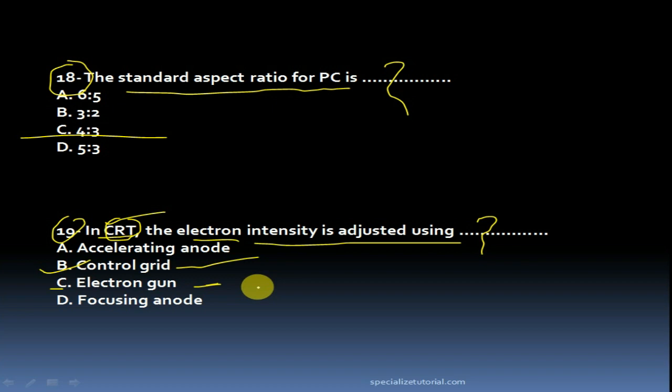So now the question is, how does the electron gun work? An electron gun starts with a small heater, a lot like the hot, bright filament of a regular light bulb. It heats a cathode, which emits a cloud of electrons. Two anodes turn the cloud into an electron beam, and the accelerating anode attracts the electrons and accelerates them toward the screen. Now, what is basically the accelerating anode?